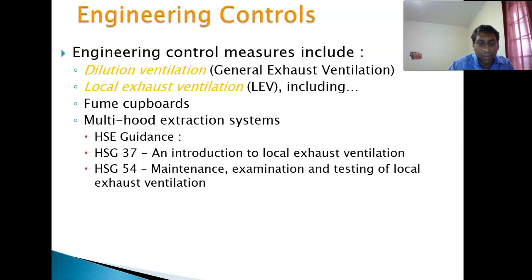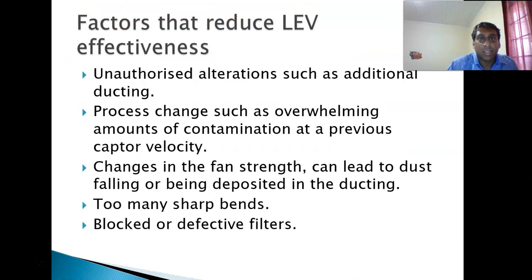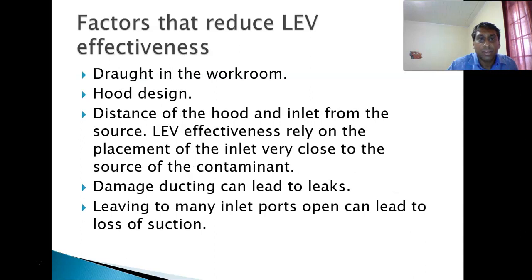Perhaps a draft in the workroom, poor hood design, greater distance. The LEV effectiveness relies on the placement of the inlet very close to the source of contaminant. Damaged ducting can lead to leaks, which may hinder the transport velocity. Leaving too many inlet ports open can lead to a loss of suction. Unauthorized alterations such as additional ducting or modifications.